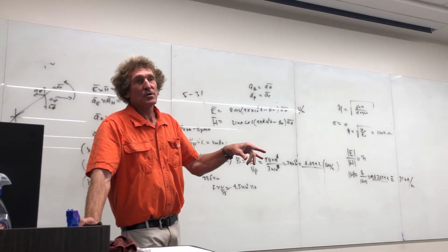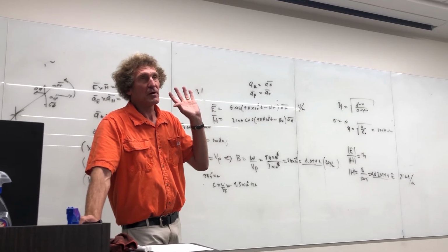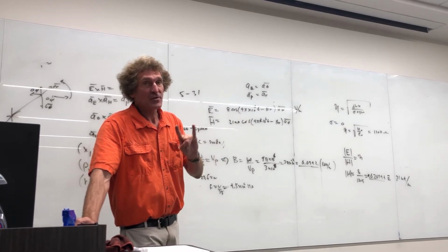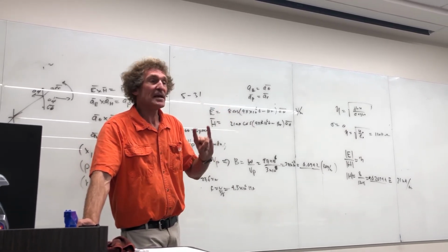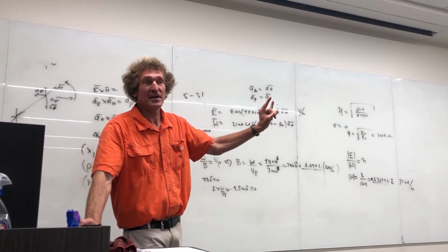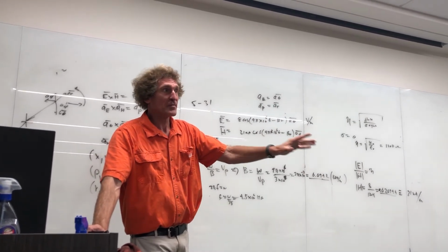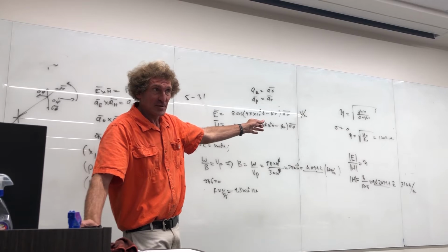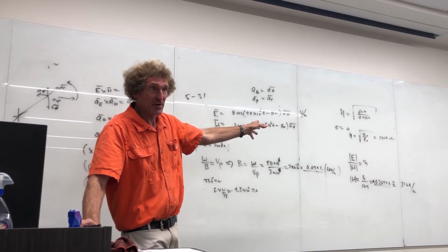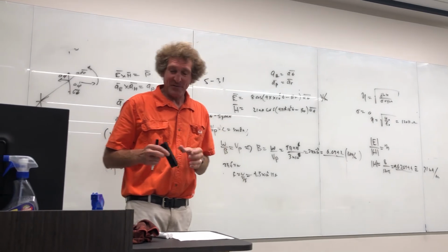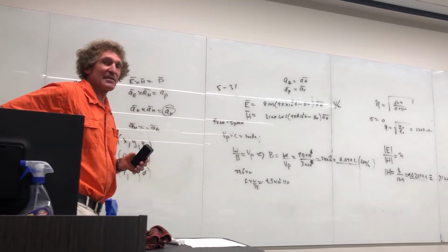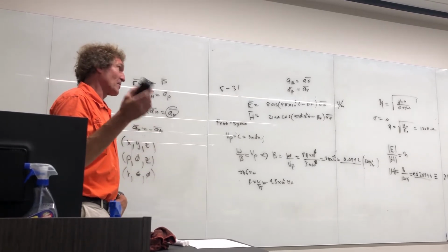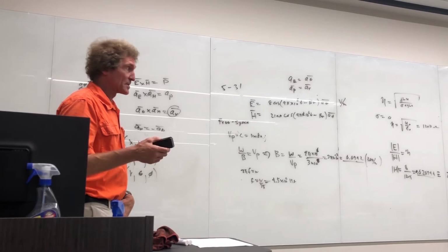And MATLAB, by the way, has functions that go from Cartesian coordinates to spherical. They give it in terms of the aircraft industry or the aeronautical industry: R, then elevation, and then azimuth. So I'm going to warn you, when you go Cartesian to spherical in MATLAB, you don't get spherical coordinates associated with the theta and phi that we're using here. Just remember these things, because you're going to save yourself a lot of anguish by not assuming theta is the same measurement for all papers and discussions that you see.